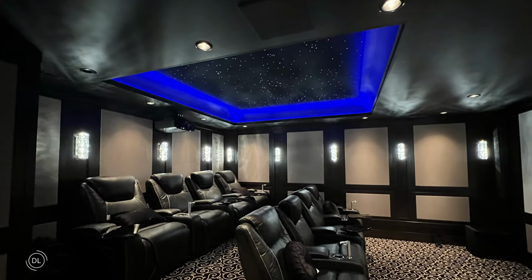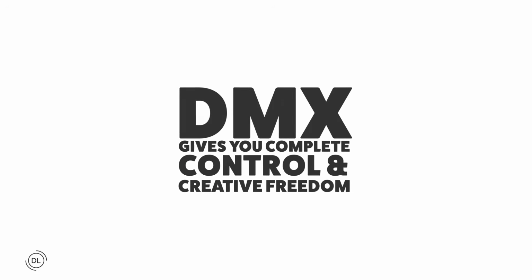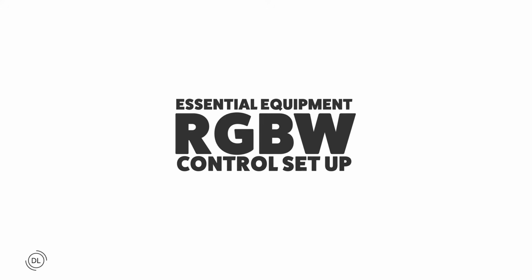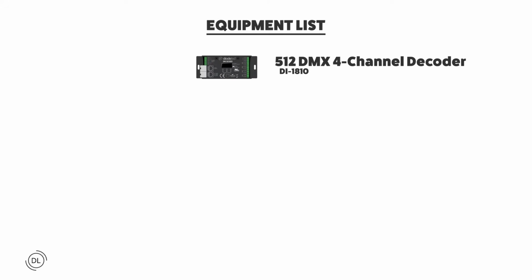From creating cinematic lighting in your home to programming multi-fixture scenes for events, DMX gives you complete control and creative freedom. Let's walk through the essential equipment required for a basic RGBW LED tape lighting control setup. Before you get started, gather the following essential components from Diode LED. 512 DMX 4-channel decoder. This device translates DMX signals into understandable commands for your lighting fixtures. They are essential for controlling LED tape light and certain types of lighting fixtures. In this case, the tape light is not DMX ready and requires a remote DMX decoder.